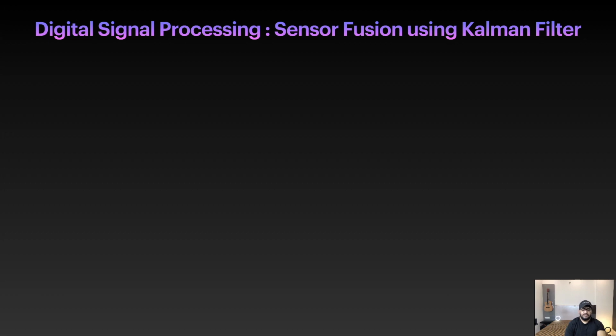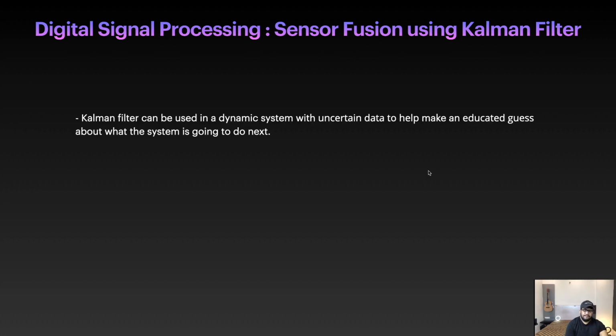So technically speaking, you can definitely use a complementary filter, but it is not as fast. It's really costly on memory, space and computation. So in the drone industry, in drone hobbies, the firmware we use for our flight controller implements something called Kalman filter, and not complementary filter. Maybe some previous firmwares had complementary filter, but nowadays I've seen everyone using Kalman filters. And why? I've already told you the advantages of Kalman filter over complementary filter. So let's talk about that.